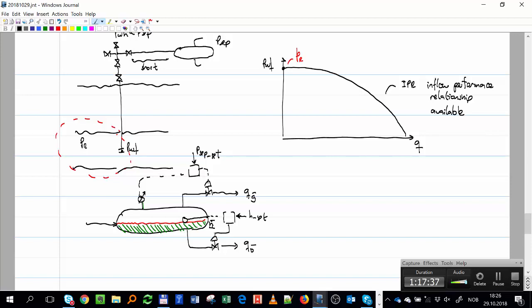So those two controllers, the level controller and the pressure controller, make sure that my separator is always at a constant pressure. Anything can come in. I can change the rate, high or low, it can fluctuate, doesn't matter. That system should be robust enough to keep my separator pressure constant, no matter what.